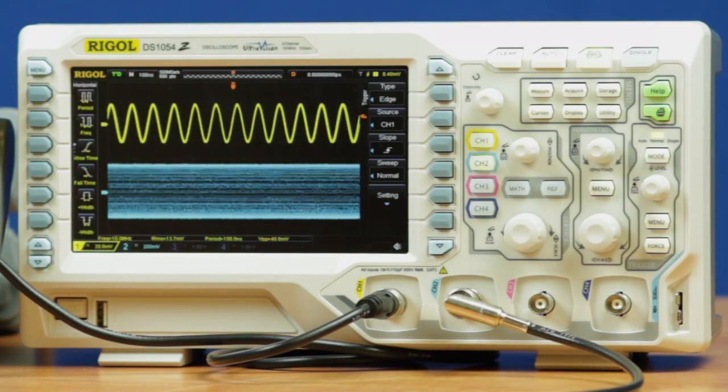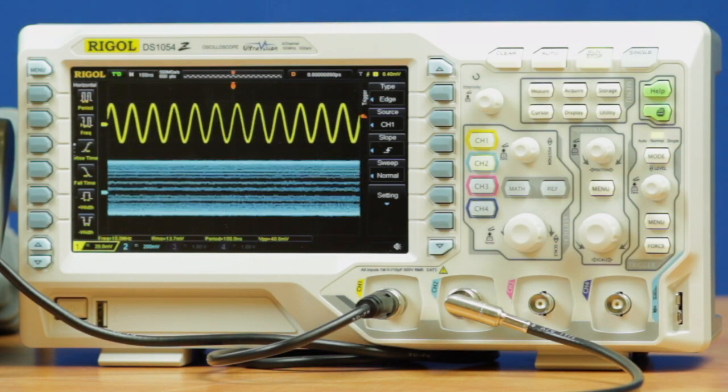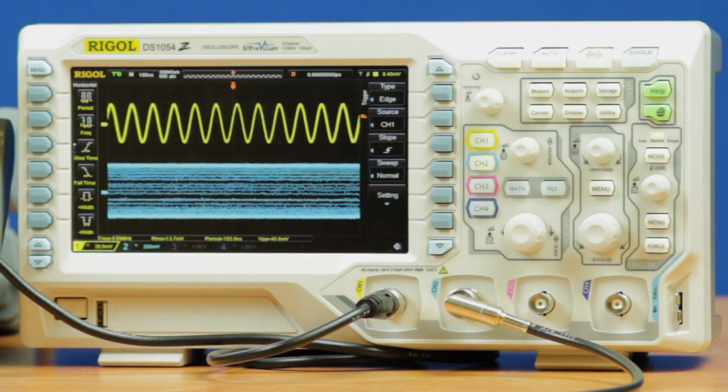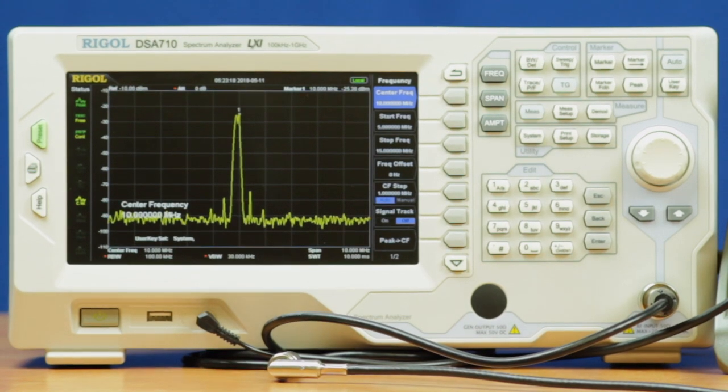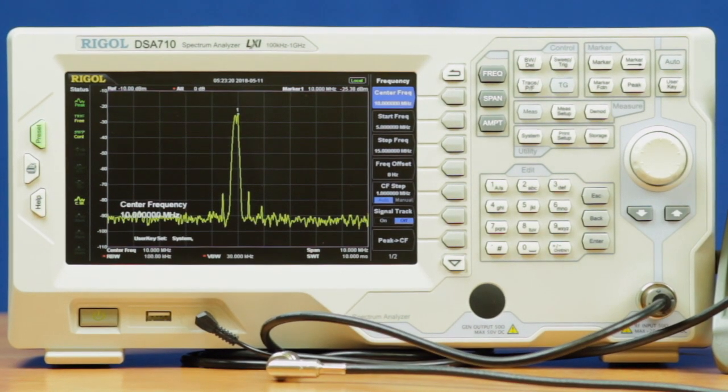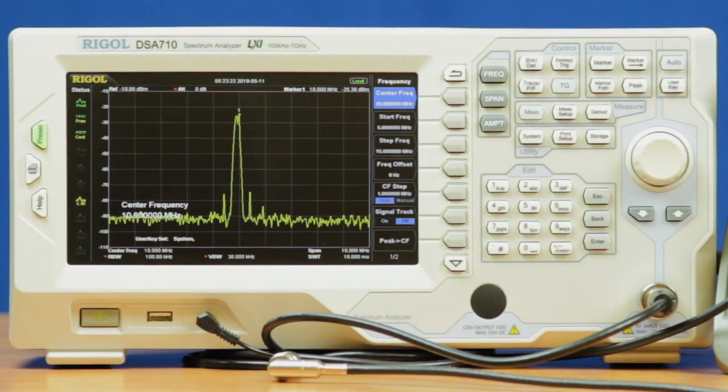But really, there's no settings in the scope where we can easily see the change in frequency because the two frequencies are just too close together. However, the spectrum analyzer is picking it up nice and easily because it's able to completely demodulate that signal, which we can see in the bits here as we move out to the 500 microseconds. So at a 1 kilohertz frequency, that bit is changing, and the spectrum analyzer cleanly can pick out the highs and the lows, even though those frequencies are close together.